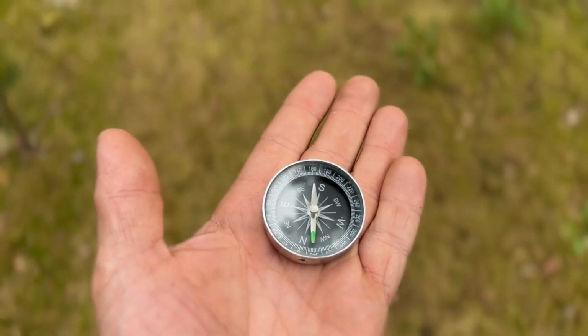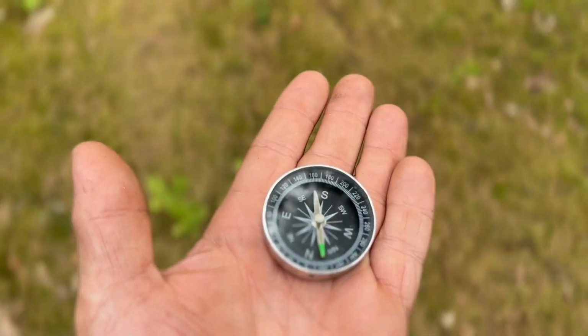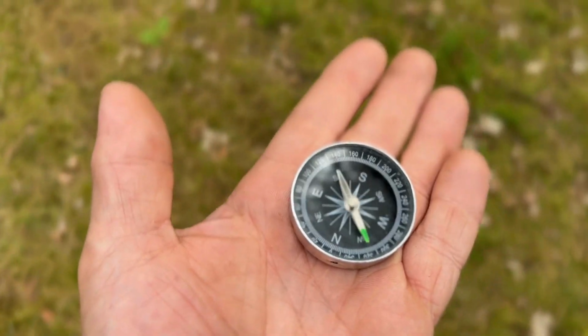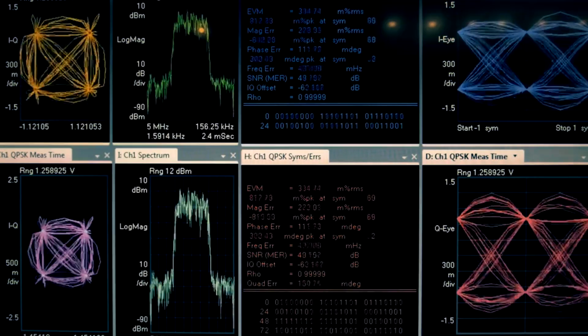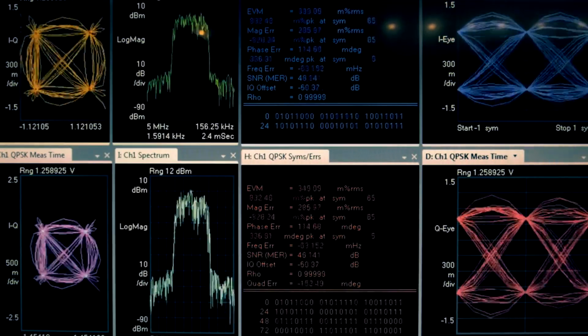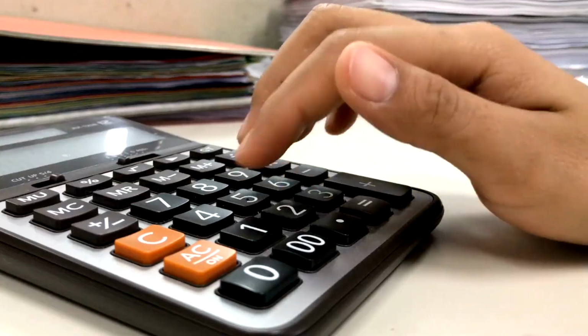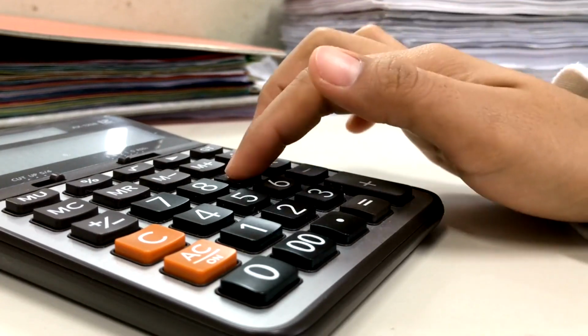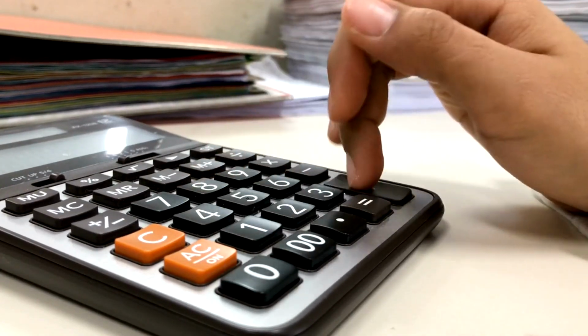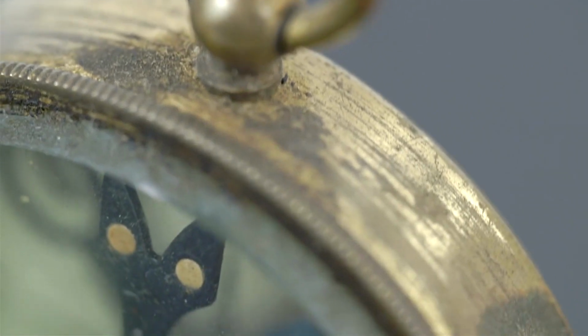6. Calculate the magnetic bearing and compare this to the compass bearing. The difference is deviation east or west. 7. Plot the deviation onto a table to obtain a deviation curve. 8. From this table you can then calculate the deviations for the headings in between the 8 bearings you took. 9. East should match west deviations.